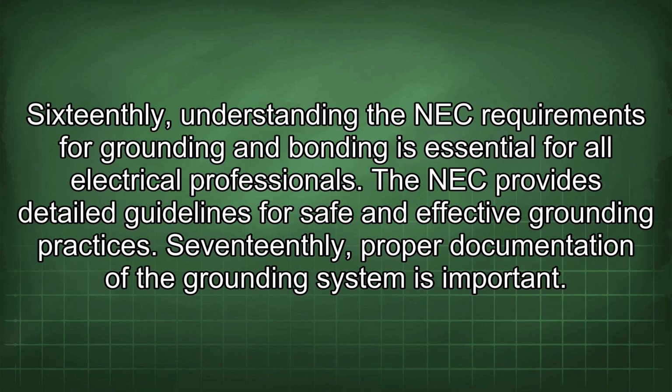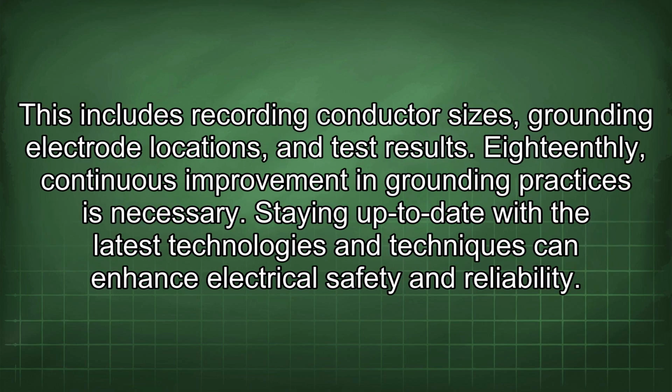Sixteenthly, understanding the NEC requirements for grounding and bonding is essential for all electrical professionals. The NEC provides detailed guidelines for safe and effective grounding practices. Seventeenthly, proper documentation of the grounding system is important. This includes recording conductor sizes, grounding electrode locations, and test results.